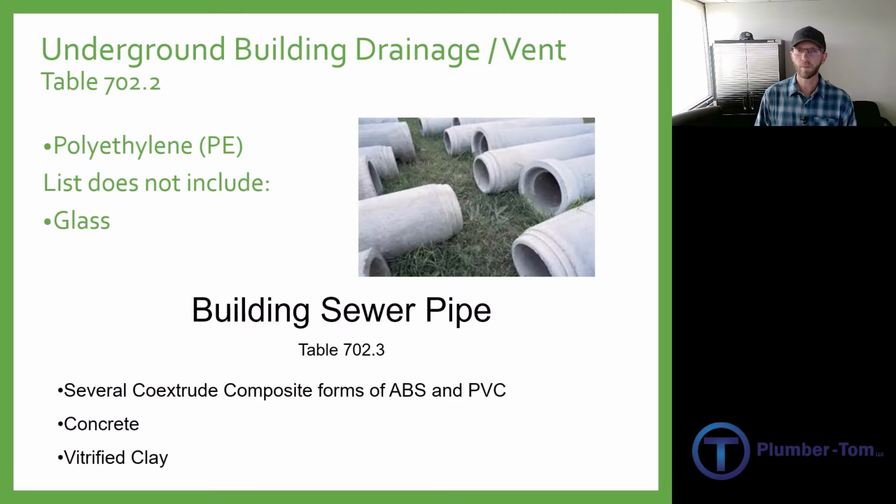It has a thinner wall. It's used specifically for sewer pipes underground. Not something that you would use inside the building, but definitely an option for sewer pipes. Concrete and vitrified clay are also approved for building sewer pipes.